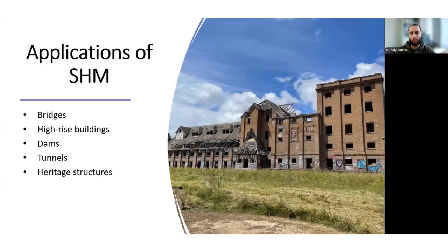Now, the process of structural health monitoring involves several key steps to assess and track the condition of a structure over time. It begins with the installation of sensors, such as strain gauges, temperature and displacement sensors, or with various forms of NDT testing and inspections on critical parts of the structure. With newer structures, the installed sensors continuously or periodically collect data related to these changes, such as loads, vibrations, and other environmental conditions. This data is then sorted, processed, and analyzed using specialized software.